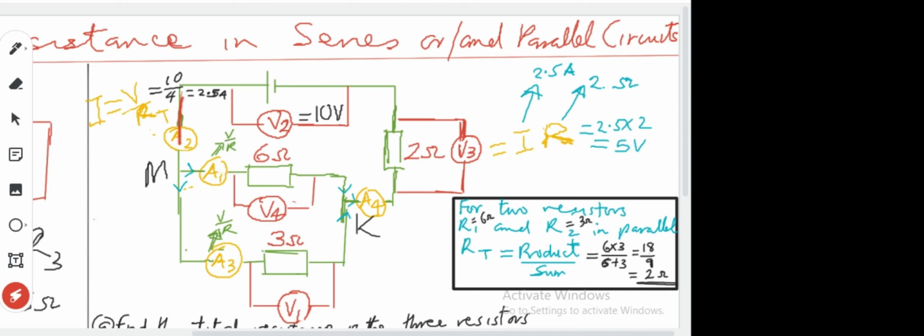If you notice, anywhere I have a voltmeter, I have to add another line to connect it. So voltmeters are connected in parallel. But when connecting an ammeter, it goes on that same route where you want to measure the current. Because current through, it should be along that same route where the current is flowing, because current is the same everywhere in series.